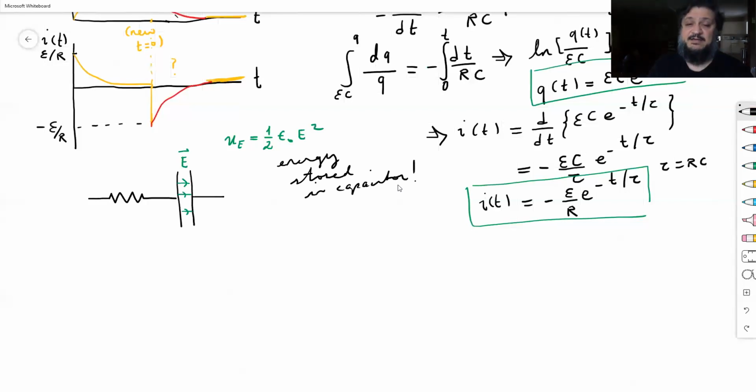They say, even if you unplug it from the power, do not try to open it. Take it to a service repair professional. And why? You may get shocked, because there's energy stored there. If you short it with your finger, you may feel a shock. All right, capacitor discharge.